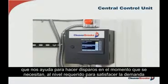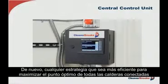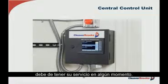which intelligently stages the boilers to fire when needed and either allows them to fire only at the rate required to meet demand or fire in unison, with the online boilers firing at the same rate to meet the demand. Again, whatever strategy is most efficient in terms of maximizing the sweet spot of all the connected boilers, which will have to be called into service at any given time.